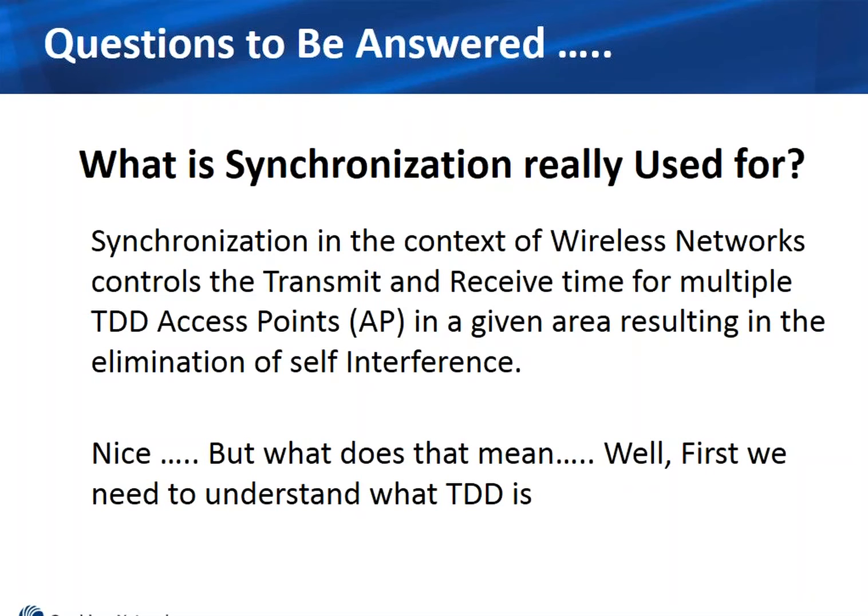Interference is a killer of throughput, a killer of efficiency within wireless radio solutions. Meaning if I have a radio that's spec'd for 100 megabits throughput, just to keep things simple, I should be able to get 100 megabits of capacity between point A and point B over a wireless link. Great.